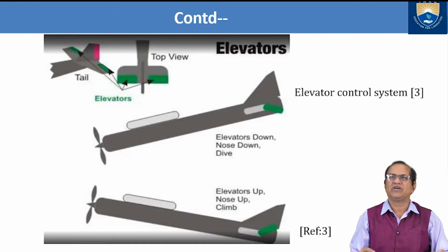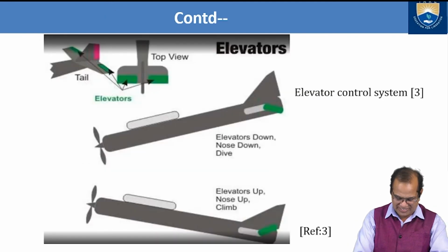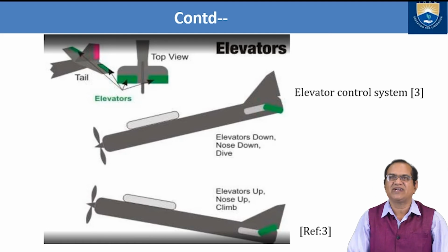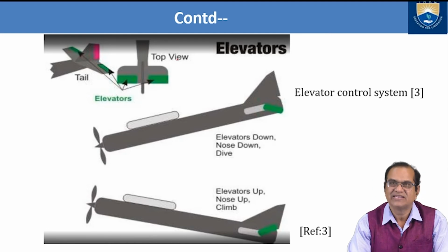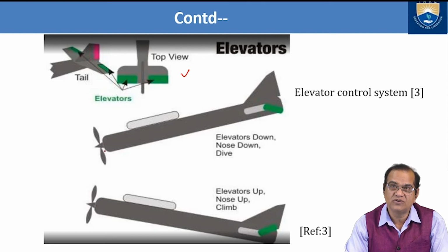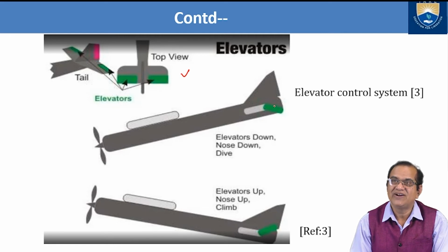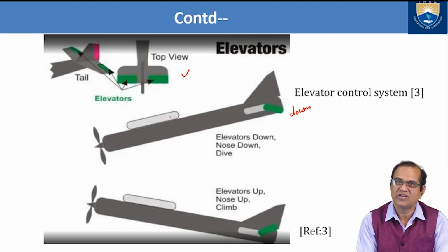Here I am showing how the elevators are working. You can see the top view here, and these are the elevators fixed here. If you want to make nose down, this elevator has to go down. Here it is down. Elevator down, nose down, dive. So the aircraft will start diving like this.